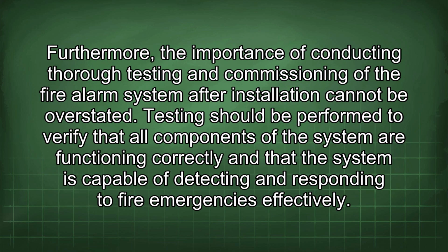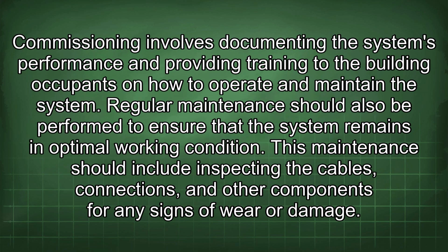Furthermore, the importance of conducting thorough testing and commissioning of the fire alarm system after installation cannot be overstated. Testing should be performed to verify that all components of the system are functioning correctly and that the system is capable of detecting and responding to fire emergencies effectively. Commissioning involves documenting the system's performance and providing training to the building occupants on how to operate and maintain the system. Regular maintenance should also be performed to ensure that the system remains in optimal working condition.